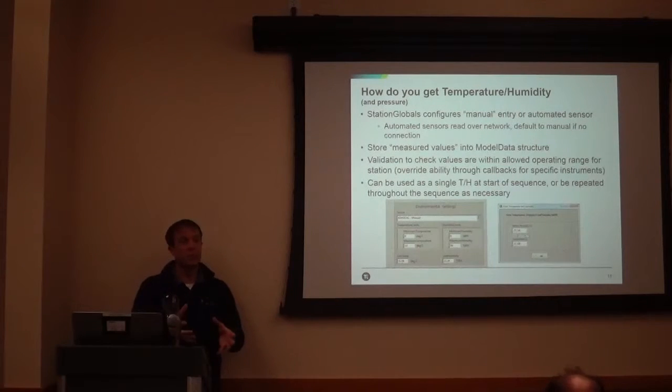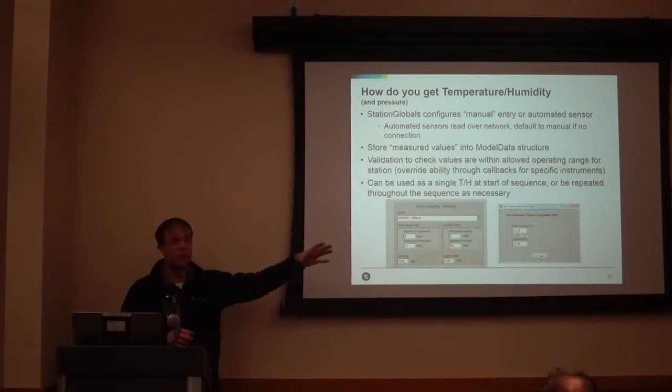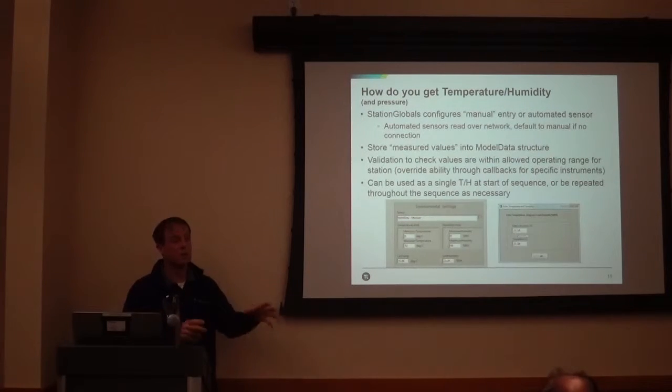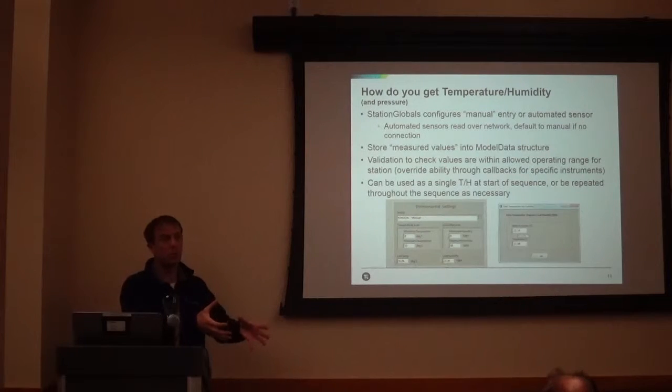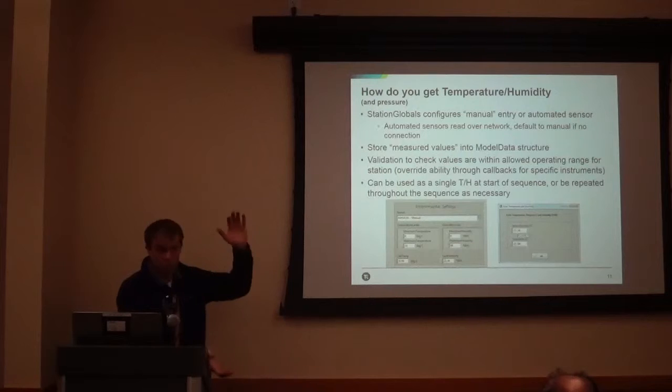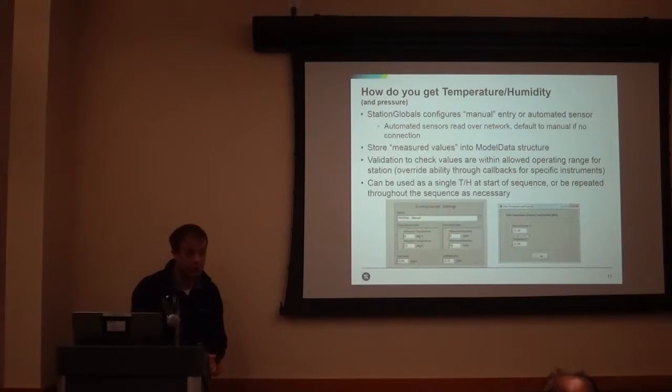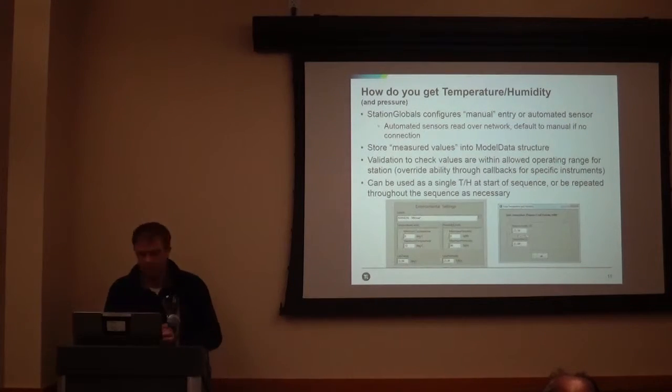But then we'll take that same test procedure with slightly modified limits and expect to run it on an instrument that's in a temperature chamber. And so for that test system that's hooked up to the temperature chamber, we get in and say, hey, pushing it to 50 degrees C is acceptable now, as opposed to expecting 23, 24. Okay.